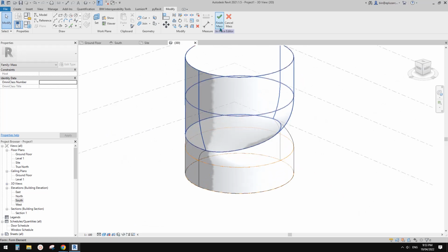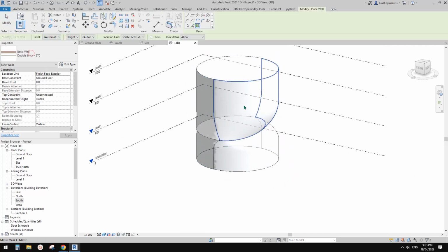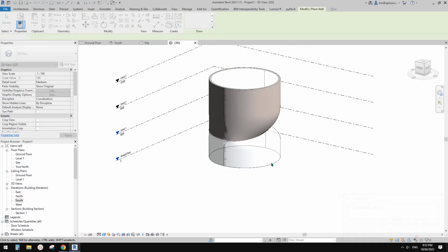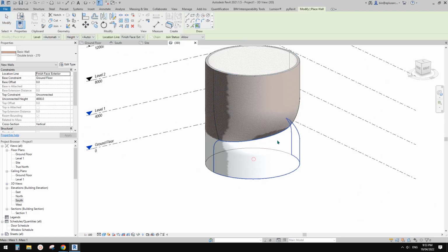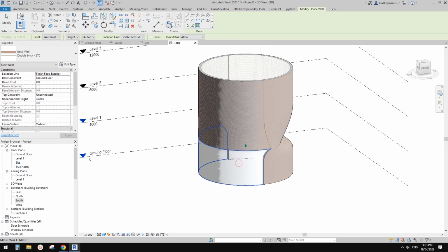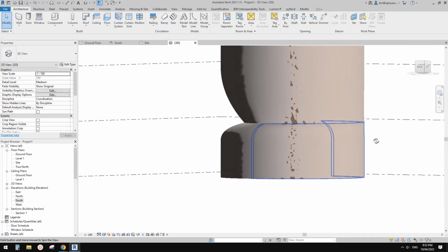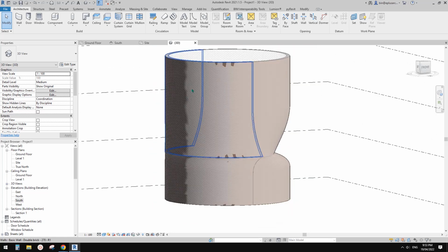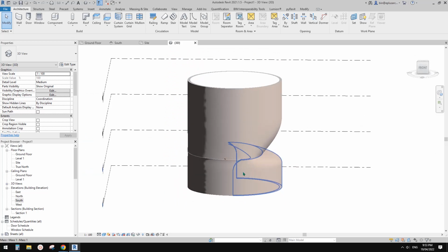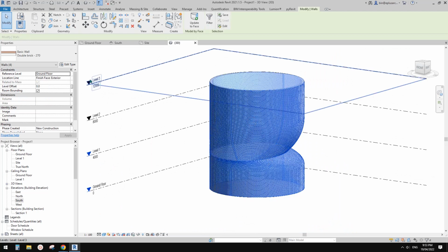This is a shape, and then we can finish this massing, and then we can just go create a wall by face and pick these and create a wall onto it. Okay, it seems you might have some issue. You should be able to create walls, no problem, but sometimes you will have some issue to join them perfectly because they are not perfectly vertical. So yeah, let me just select all of them, maybe change them to a generic wall.